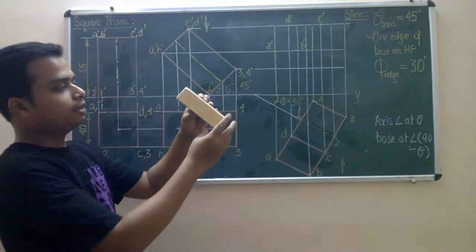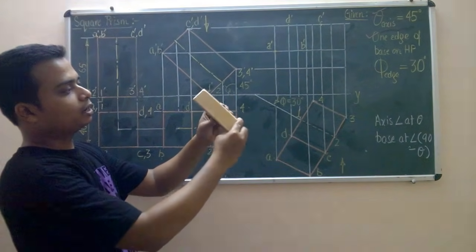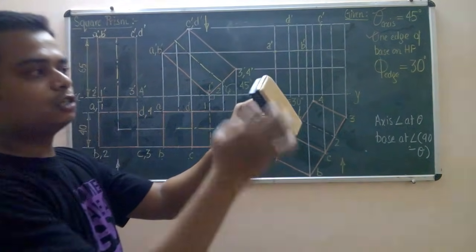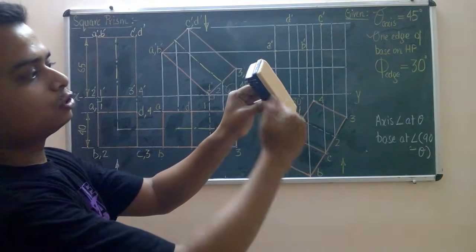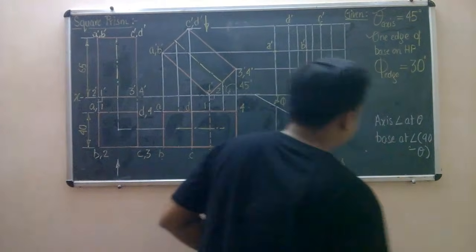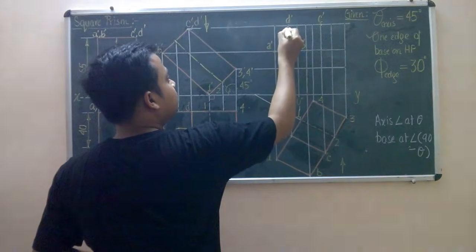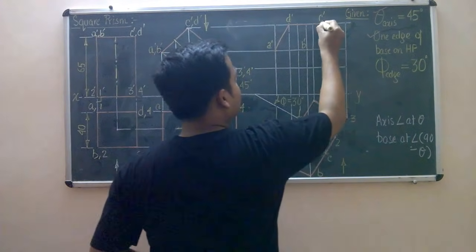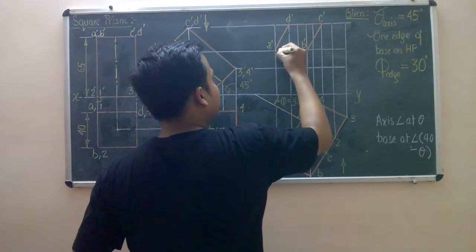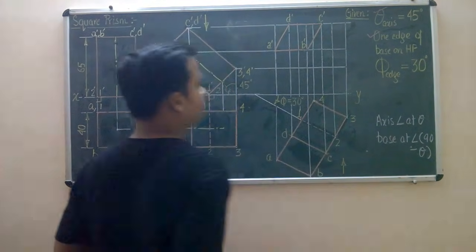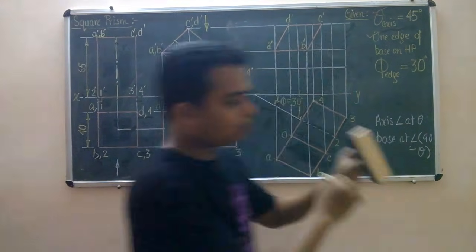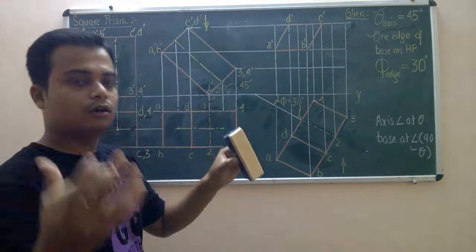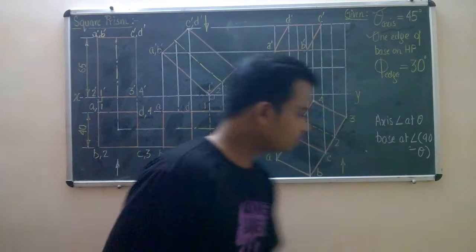One thing which is very interesting to see, step 1, step 2 and this is step 3. This portion is evident from the front. If you look at this carefully, this portion is evident from the front and this portion is also evident. So anything that is evident, anything which can be observed must be drawn using solid lines. And in this case, whenever you draw this figure in your drawing sheet, make sure that you are using an edge pencil to accomplish this. All the 4 edges, step 1, step 2, step 3, all the 4 edges at the top, that is A, B, C, D, are or can be seen from the front.